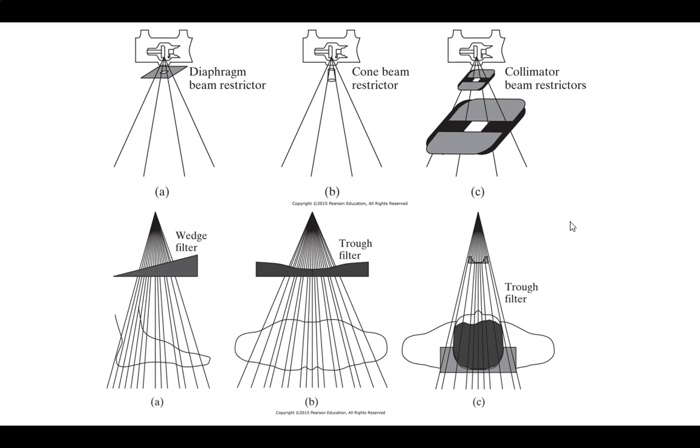Right. The filter is usually a material that's not going to break down as badly, and it's scheduled to be replaced regularly. Generally, you don't want radiation hitting a metal structure unless you're going to be replacing it on a fairly regular basis, because high amounts of radiation hitting metal over time makes that metal become slightly radioactive. So we generally don't like that.